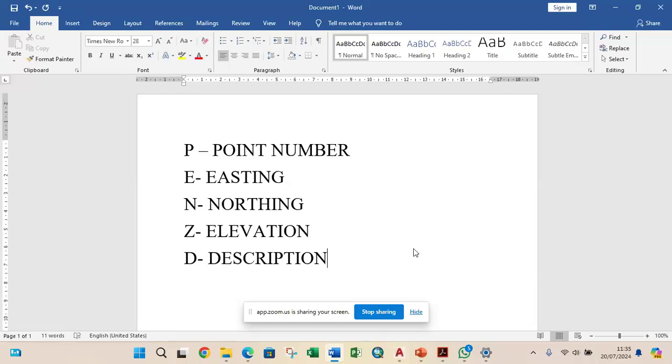This description will also aid you if you didn't go for the reconnaissance survey with him. It will help you know what is along the project corridor. So when you are designing your horizontal alignments, you know how to navigate and avoid the demolition of buildings. You know the number of electric poles and the transformer you locate, or if there's a river crossing at that point. The description established on site will still guide you if you didn't go for the reconnaissance survey with him.